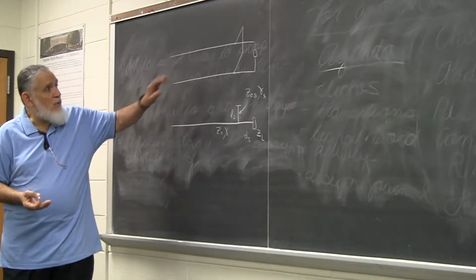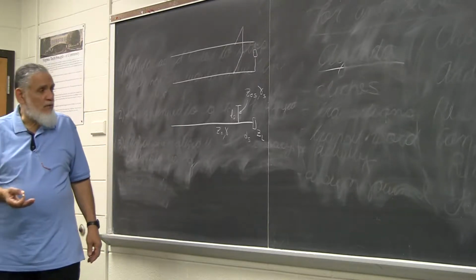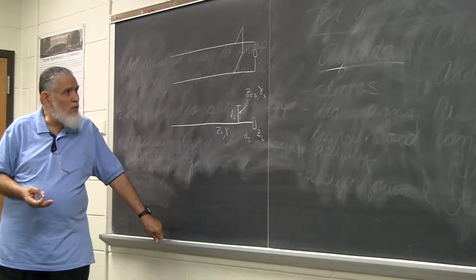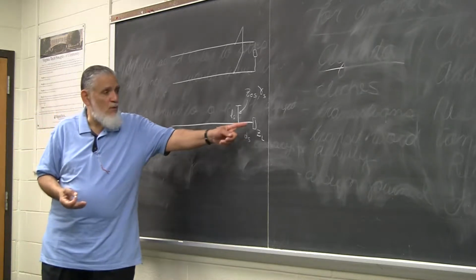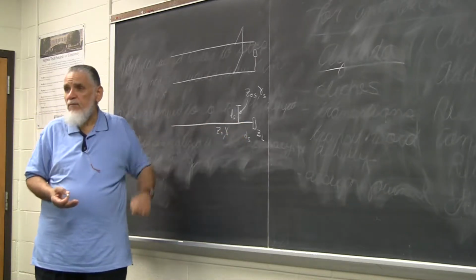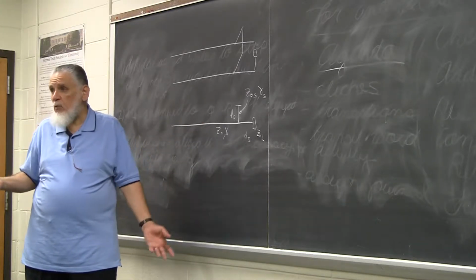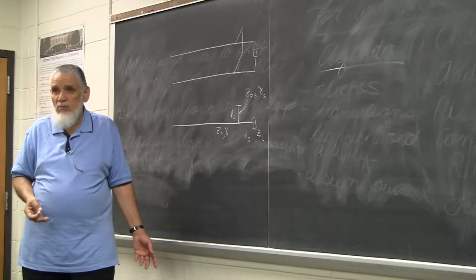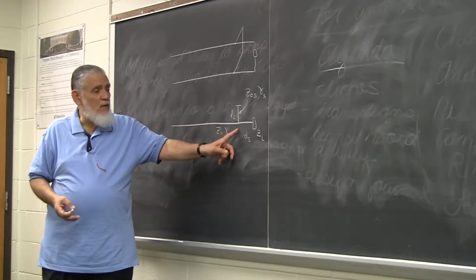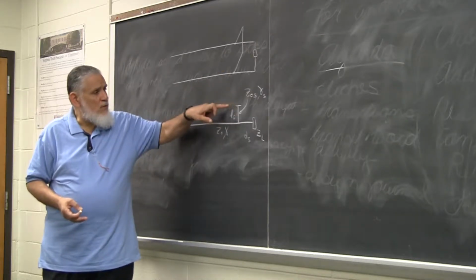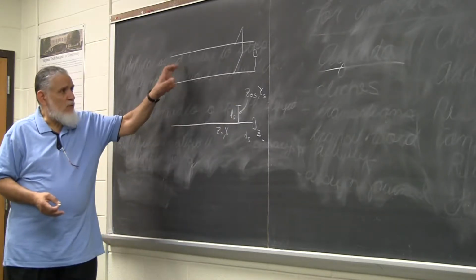The schematic that we usually draw is like this, but this is a simplified schematic that we often use so we can get over drawing nodes and lines crossing each other and all that. Basically, here's your transmission media, which can work as well for waveguides, because the waveguide doesn't have two wires, right? The waveguide is simply a transmission media. So you have a transmission media, and somewhere in here you add a stub. In this case, it's a shunt stub, and the stub is shorted there. So this is a simplified version of the schematic that we see up there.